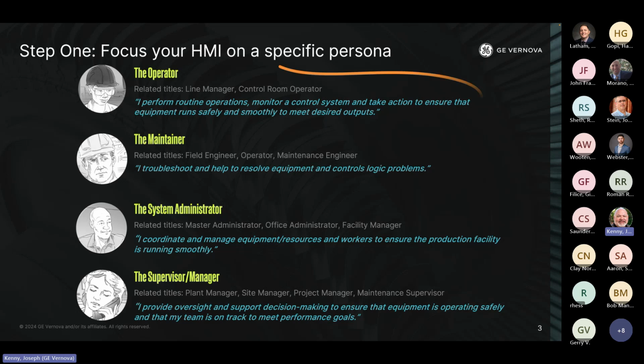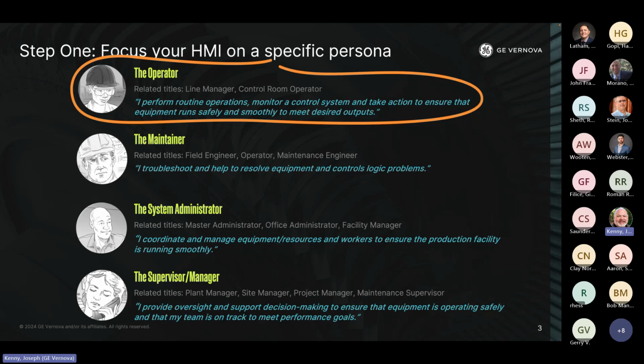High-performance HMI is when you say, I am going to design a screen for the operator, and specifically the operator's tasks. That narrows the scope of what you're doing. It will inevitably simplify the screens. In some cases, yes, you may end up designing an additional screen to cater to, let's say, the maintainer or the administrator. But the reality is, oftentimes, too much data on the screen slows the users down, and it costs more than just maintaining and developing that initial separate screen.